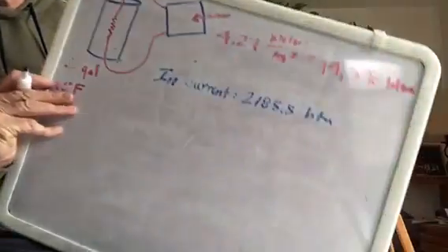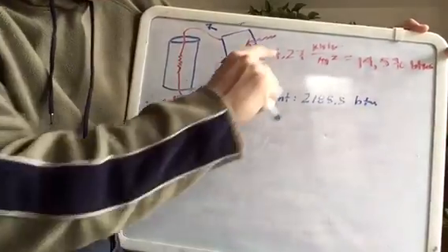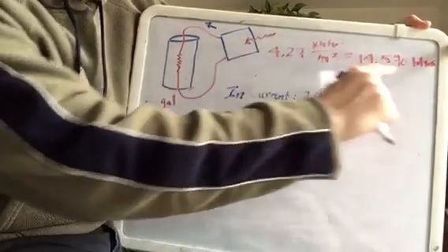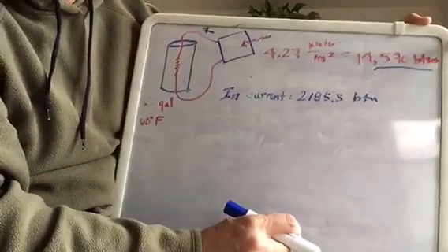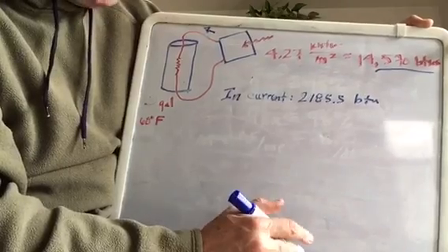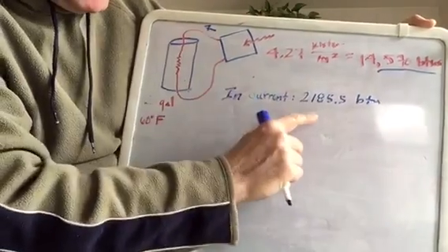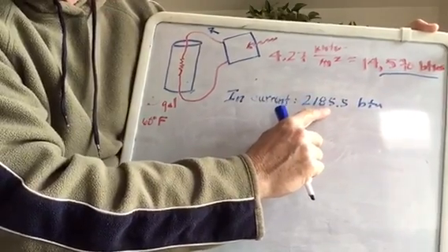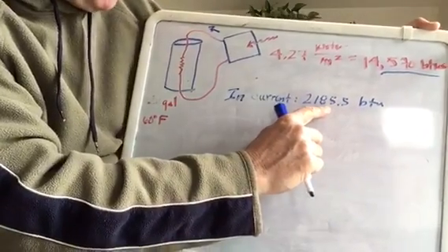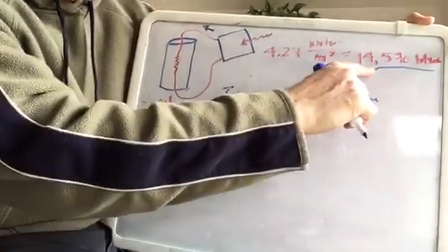Okay, so with these efficiency problems, it's kind of like a step-by-step process. So out here over the course of the day, we've got 14,570 BTUs. How much actually gets into the electricity here? How much of that 14,000 gets here? I multiplied that 14,570 by 15%, and I got 2186. So about 2185.5 BTUs.